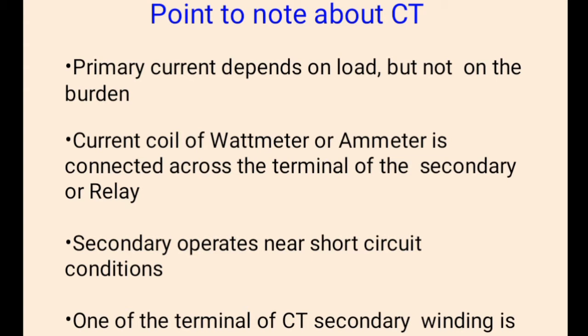The coil of wattmeter or ammeter is connected across the terminal of secondary of relay. Secondary operates near short circuit conditions. One of the terminals of CT secondary winding is earthed. Never open circuit the secondary of CT. That will cause huge damage to the current transformer.